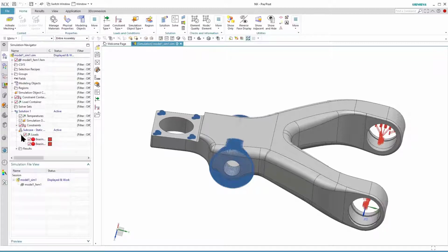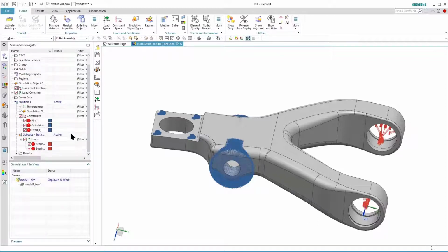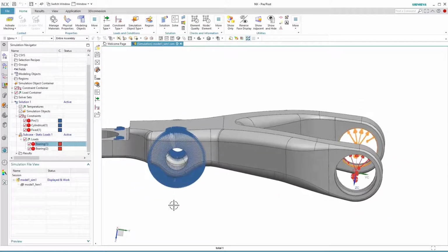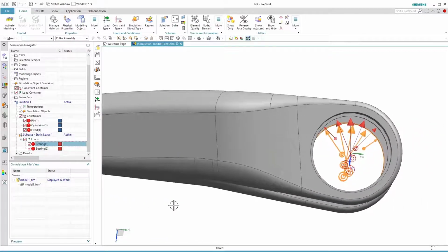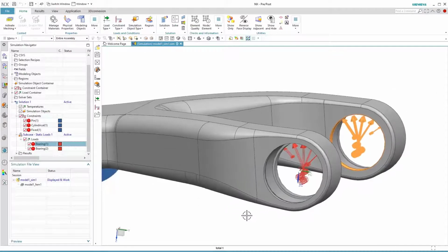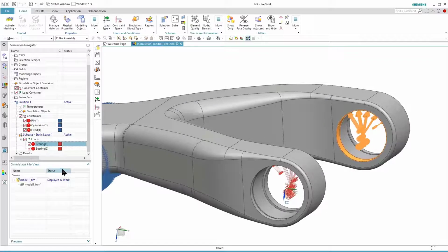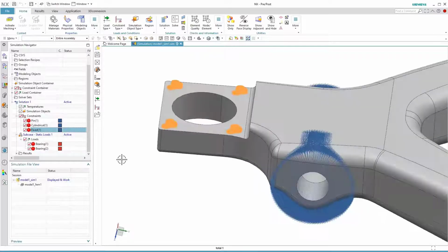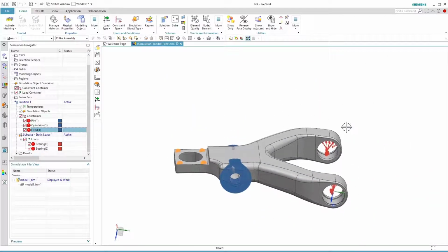In the model, the constraints are given there. They have a bearing constraint of 10,000 Newton on this surface in the direction -z, and I put it just on the surface. That's a possible contact with the axe. The axle is put in there, and also on this side I put 10,000 Newton. So these are the two cylindrical surfaces used, as I mentioned.